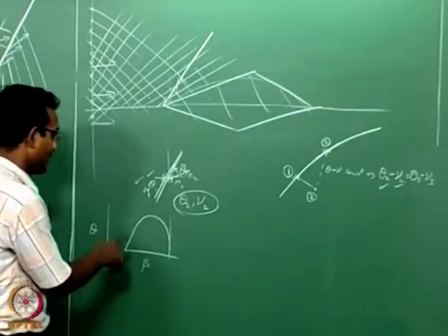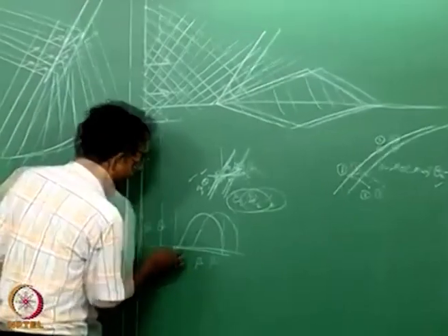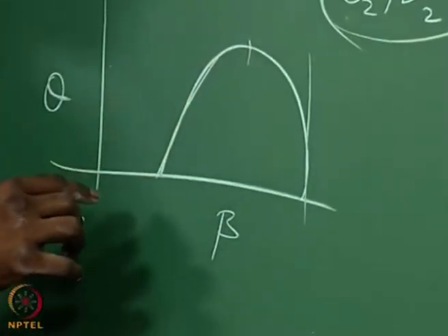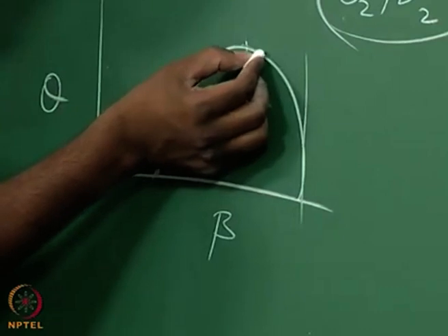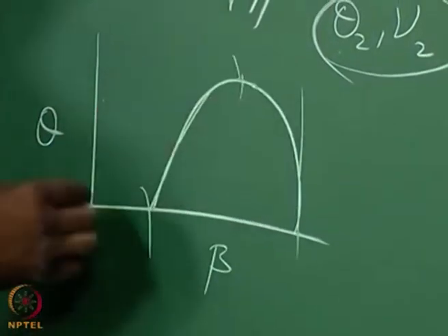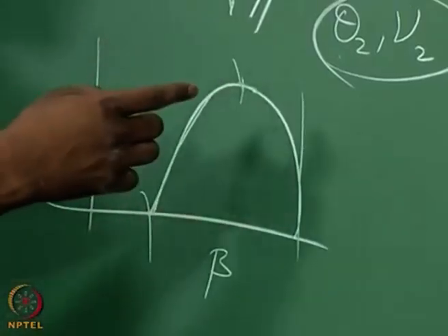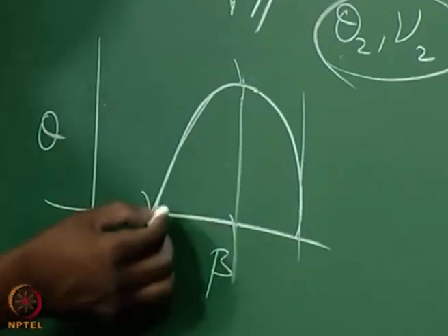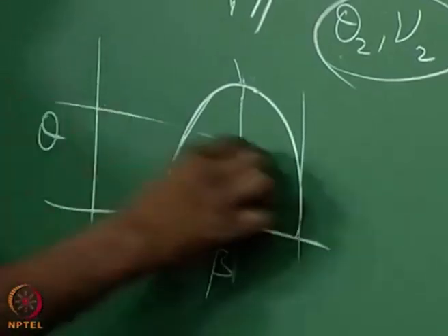Remember the oblique shock curve. I want to stay only in the supersonic section. Of course you know that it will be supersonic, even a little bit more that side, but I will stay only between mu and theta critical and I will solve for this problem. I will just keep on trying whatever beta from here to here till I get to some particular theta value